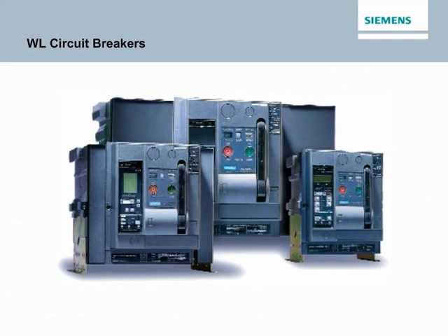LV power circuit breakers are generally drawer out mounted and may be used in switchboards or switchgear. LV power circuit breakers intended for the U.S. market conform to American National Standards Institute, the ANSI, standards C37.13, C37.16, C37.17, and C37.50, and the National Electrical Manufacturers Association standard SG3. The corresponding UL specification for LV power circuit breakers is UL 1066.